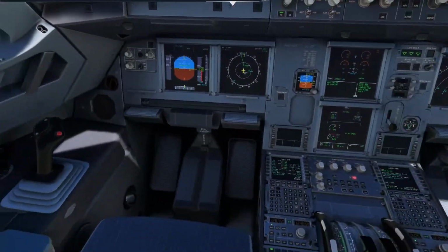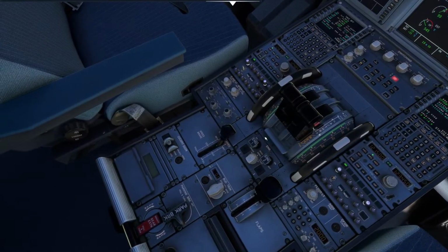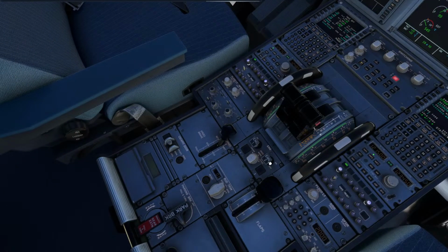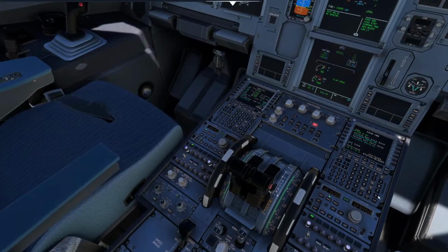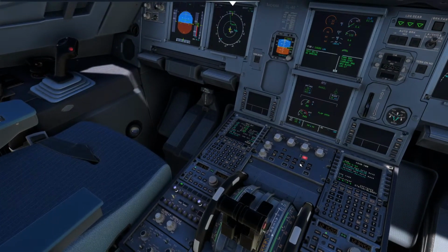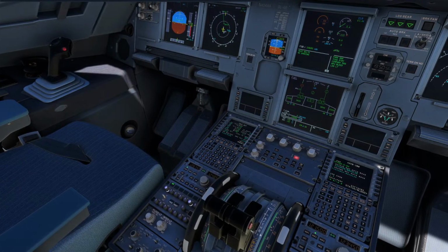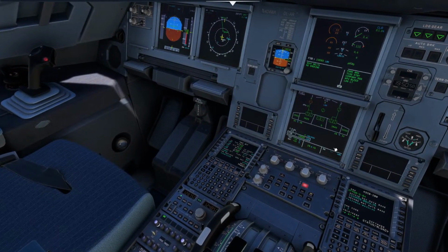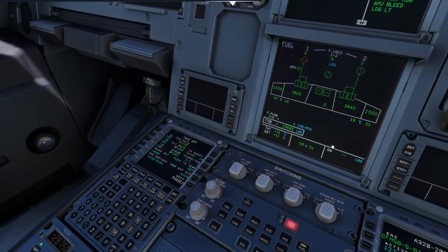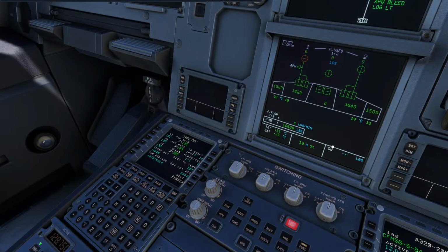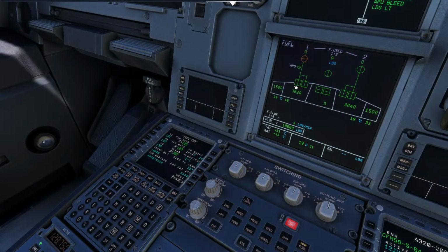We'll go over here, and all you have to do with the Airbus is start engine 2 first, simulating that there's a jet bridge or something, and we don't want to start that engine side first. Okay, engine 2. And actually, let's see here, fuel. The airplane also burns fuel. The APU, if you notice, burns fuel from the right wing. So that's the other reason why you start engine 2 first, typically.